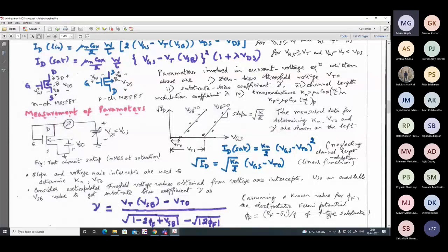Continuous, you mean to say, suppose VSB equal to 0 and VDS can go up. You see how much current is allowed to pass for a transistor, that is provided by the manufacturer. Say it is given as 5 milliampere or 10 milliampere. So we have to see that drain current does not exceed that limit. So we have to stop at some point of the drain to source potential.